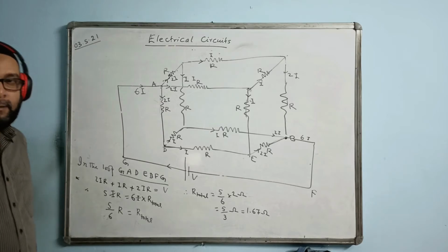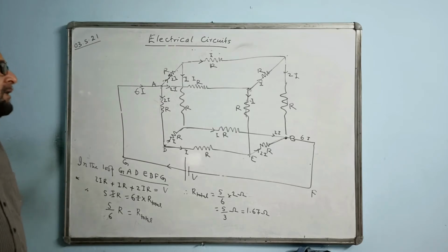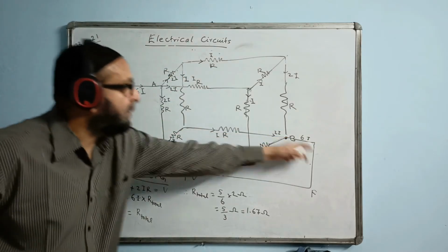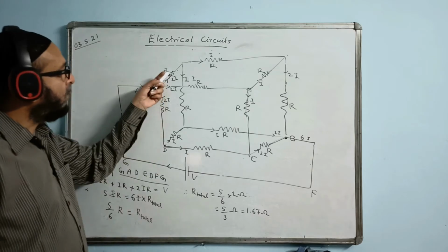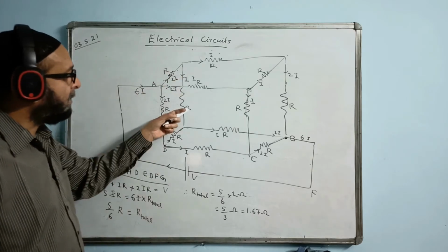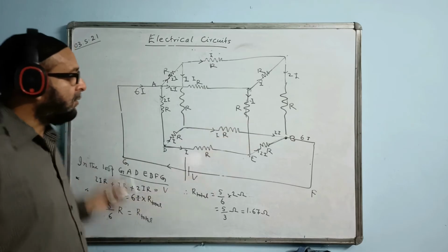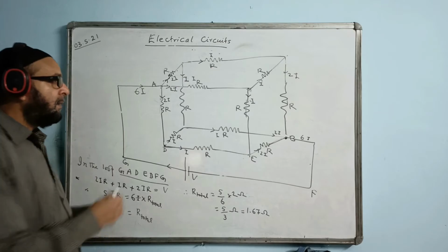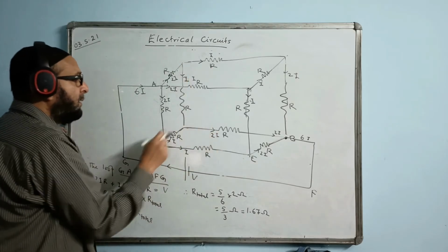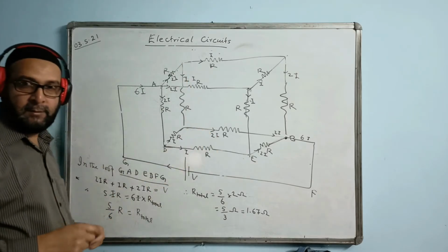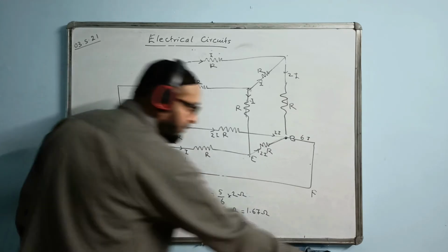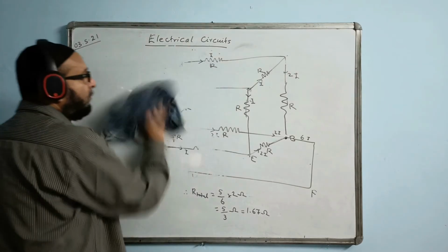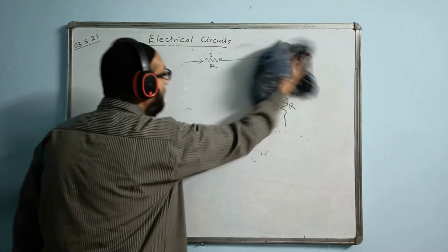Yes, sir. We can take the loop in any case. If I take the loop even this way, then also we will have the same answer coming. Here 2IR plus IR plus 2IR again, and the answer will come the same. This is 2I actually. I coming here, I coming here, becoming 2I. So Kirchhoff's law is even useful for finding the total resistance of a complicated circuit.